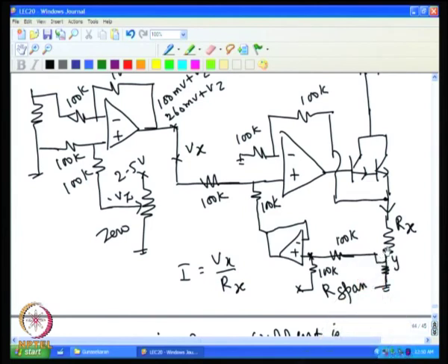Now, to make it 4-20 milliampere, we can do this, but keeping this 100 and 260 millivolt varying to 4-20 milliampere is not an easy solution, because the ratios will not match. One has to do a lot of jugglery in terms of resistance variations. Or, another possibility, we can also add the voltage at the plus input.